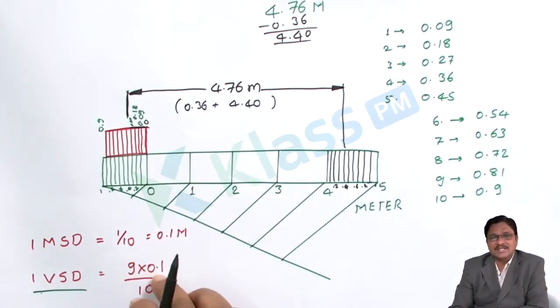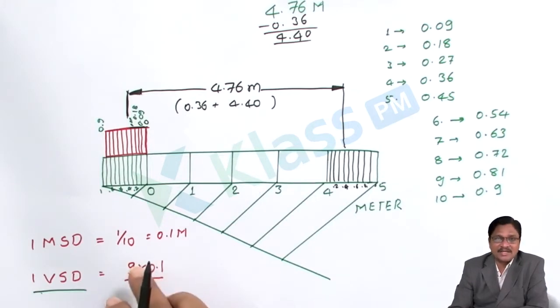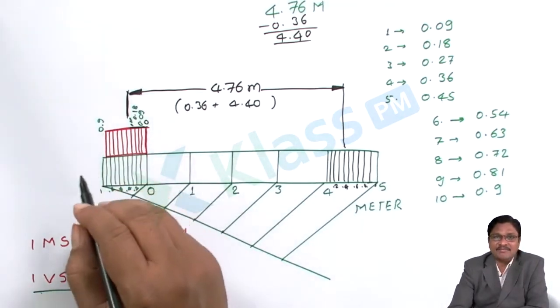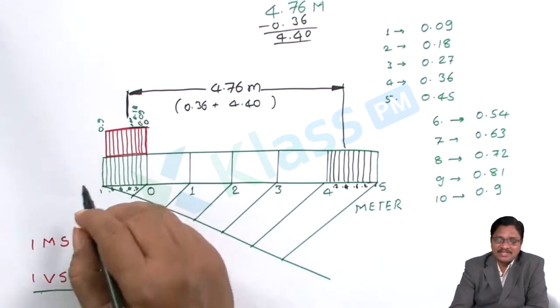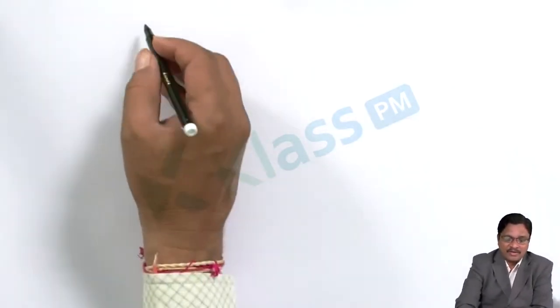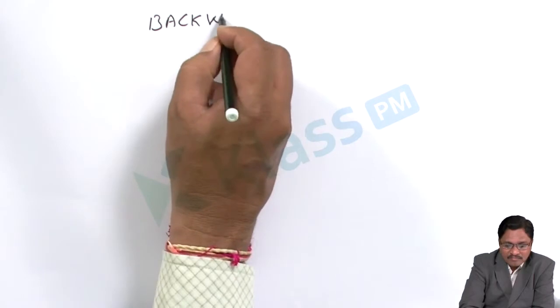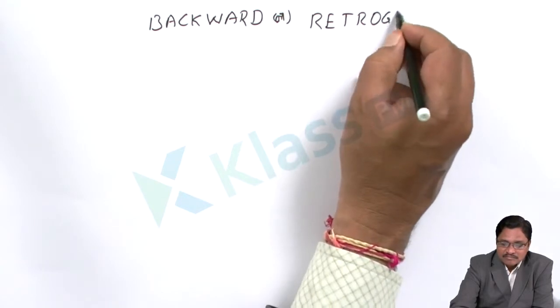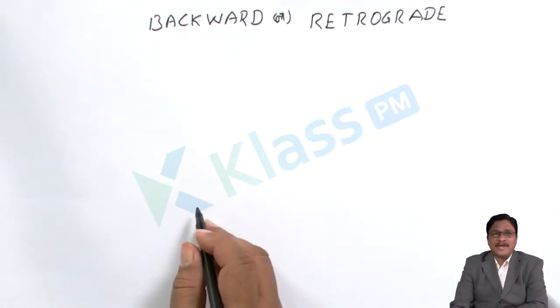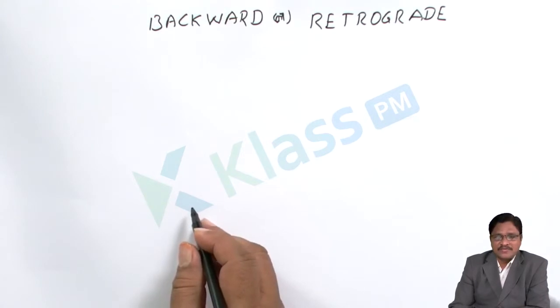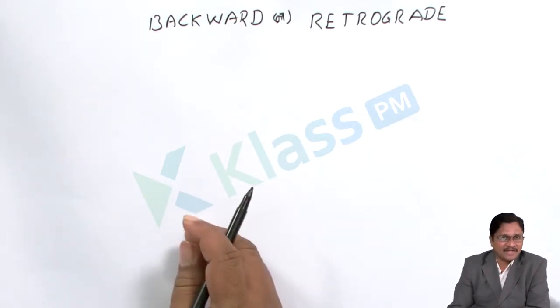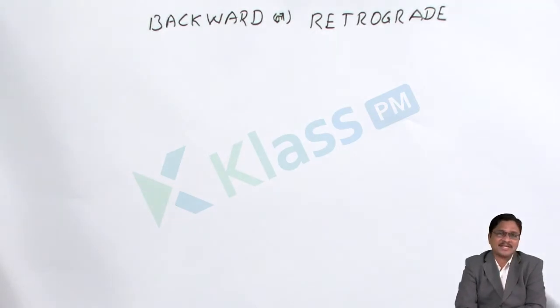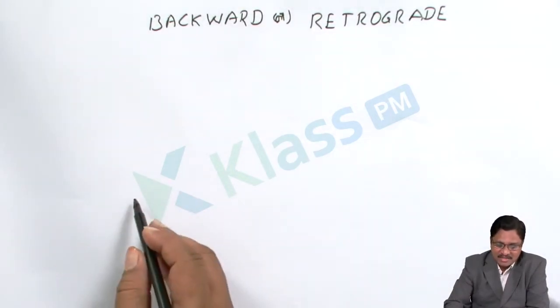What we discussed in this case is how to construct a vernier scale by the method of forward vernier or direct vernier. So let's check the same problem by the other method, backward or retrograde vernier. For the same, the RF we calculated: 1 by 40, straight away given. The LS for the particular length we are getting as 15 centimeters. The same thing you have to consider here.